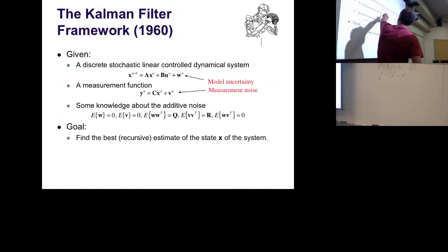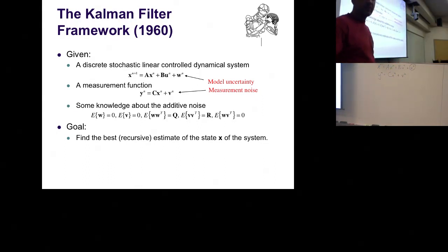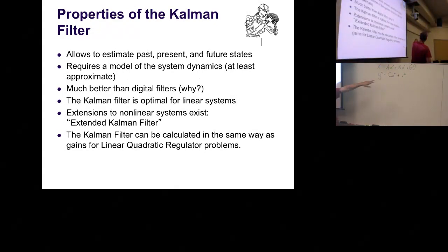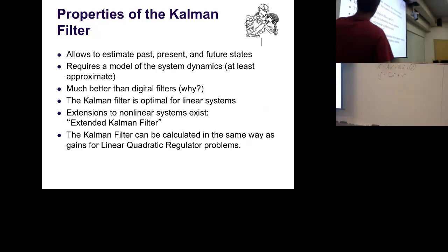Well, the future I can predict with the help of those equations. That's just a model. And if I would apply it multiple times, I can predict actually far in the future, just my confidence in this will go down. We need a model of the system, which we just saw. And it has to be good enough. Approximate works, but then you most likely inflate that W term. You will figure out that these two noise terms become a little bit twiddling parameters. There's some truth to them, and then people tweak them until they get the performance they want.